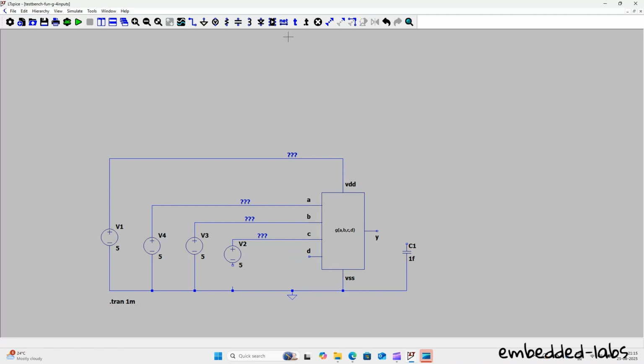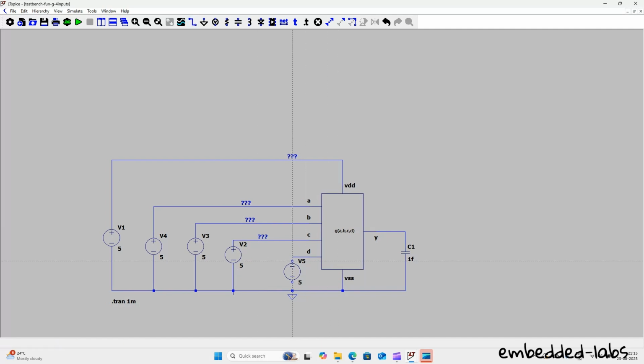Okay, now you can complete the wiring. So you go to the wire and let us say the D terminal has to be connected to the ground. The Y has to be connected to the load, which is a capacitor here. Instead of connecting to the ground, let us connect it to a voltage source. So press Ctrl C and click on this so that you can paste it here. Click on the wire button, complete this, and complete this connection. So delete this section.